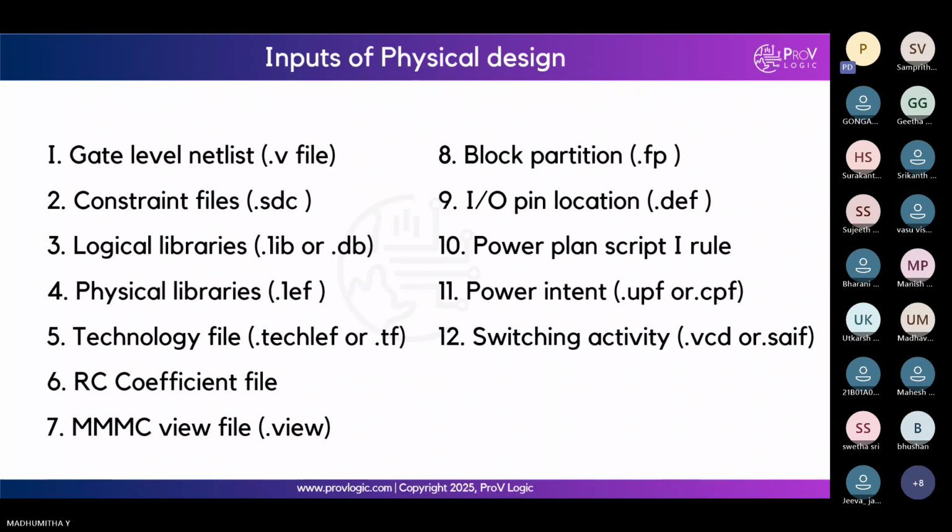How to decide how many stripes are required? Again, that depends on the requirement of our design. How many power pins, how many rails, how many straps, everything depends on how many standard cells are there in our design, how dense the logic is, and what the power requirement of this logic is. Based on this only, we will be able to decide.